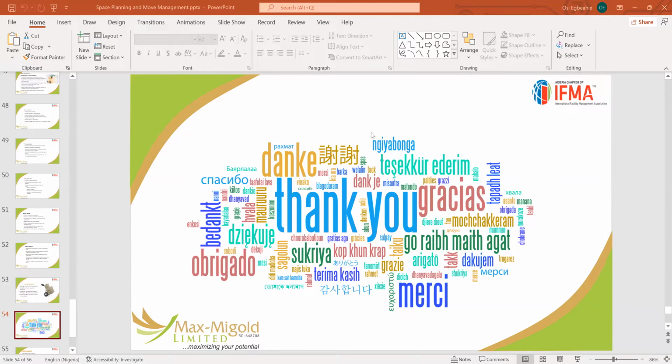Once you have that, if you have, let's say, 100 staff in the office, you multiply 3 by 100, that will give you 300. That is the minimum amount of space that you require, a minimum of 300 square meters of workable space. Normally, you add another 20% to that.